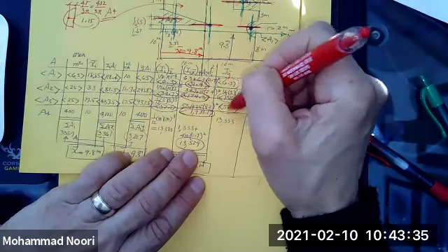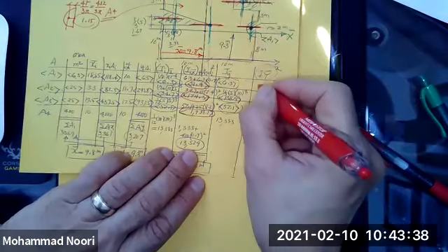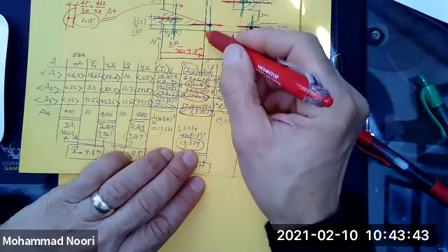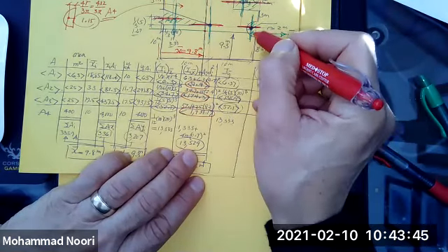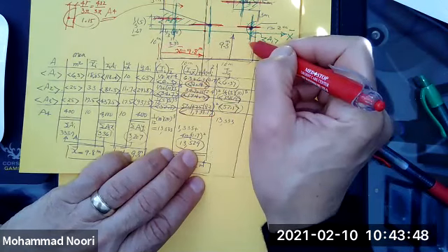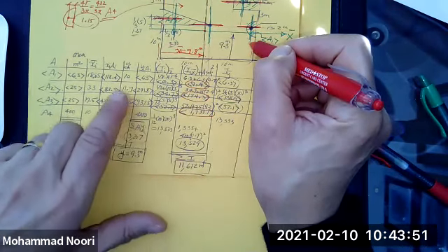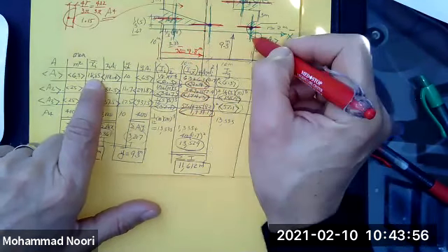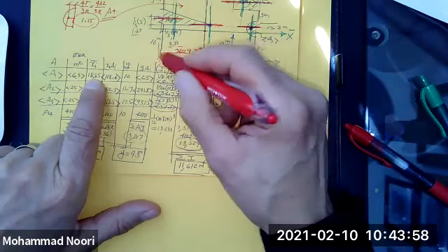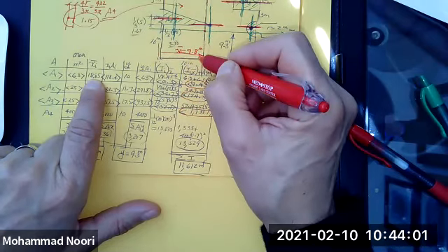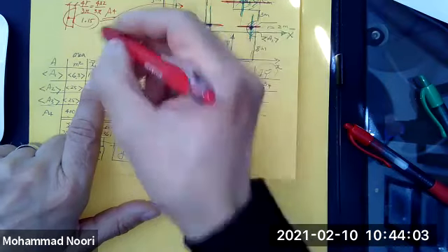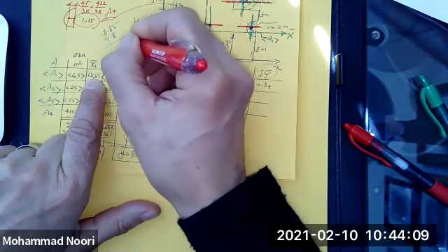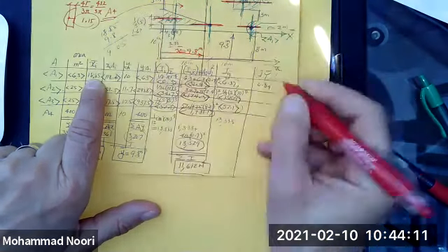Now, the last column, you want to find the moment of inertia about this axis. So you have these, just add to them. Let's say, for instance, this one would be 6.3 plus the distance from here to here. You had this distance already, which is your X bar, 18.85 minus 9.8, that'll give you 9.05.